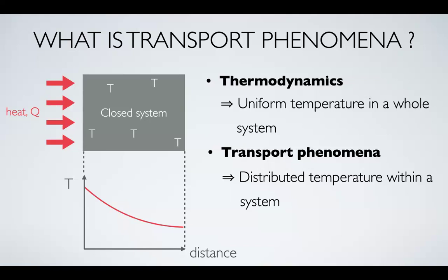All right. And what I'm going to add is that this temperature distribution along with distance here is going to change with time too. So if you keep applying heat on the left-hand side for a whole day, for example, do you think the graph will be changing or is going to be constant like this? It's going to change, right? And what is it going to change? It's going to be like a flat curve, like a horizontal line, because it's going to reach steady state.